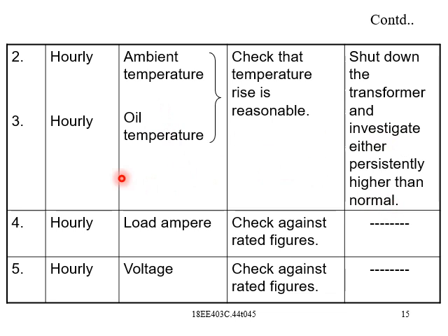The same thing is to be done for oil temperature also, and the inspection frequency is hourly. What kind of temperature of oil? Check the same temperature. If the rise is reasonable, fine; if not satisfactory, then you need to shut down the transformer and investigate if it is persistently higher than normal.